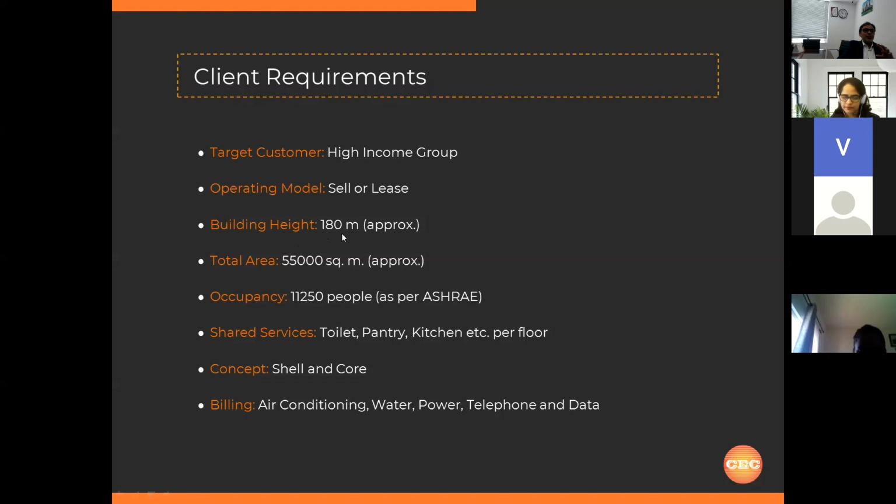That means you need to break the pressure. For such a building having a height of more than 100 meters, we need to introduce a mechanical floor, where the lower floors will be served from the ground floor, and the floors from an intermediate floor, say at 90 or 100 meters, halfway through, will be handled from the intermediate floor up to the roof.